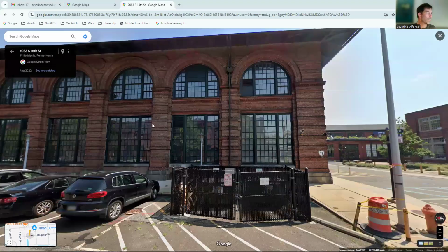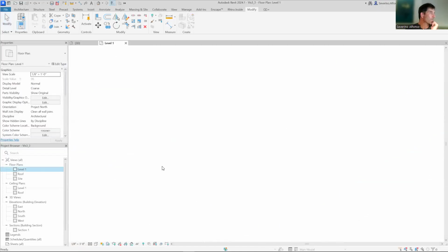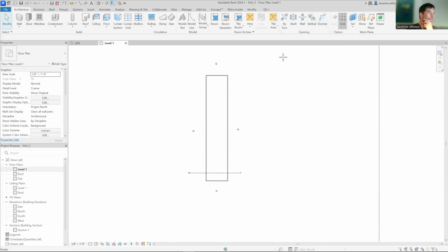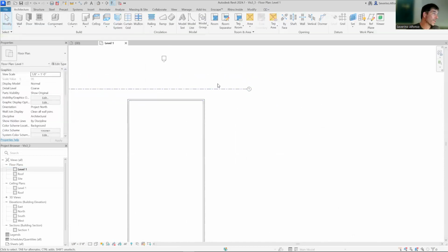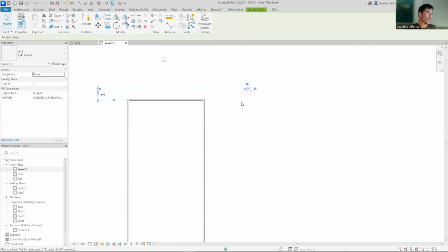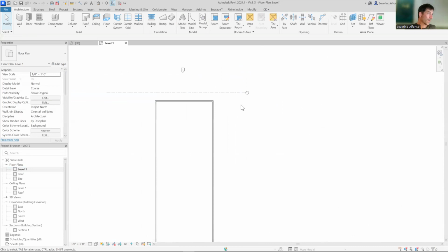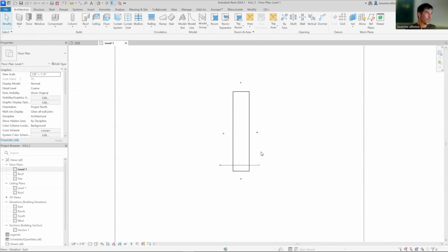Let's go back to Revit. I'll turn off the shadows. And under level 1, there's one ingredient that is quite important for us to learn, and it's the grid system. The grid allows you to generate, as the name indicates, a grid with a number. So those typically refer to structural elements in the project. I'm going to go back, Control-C to that.